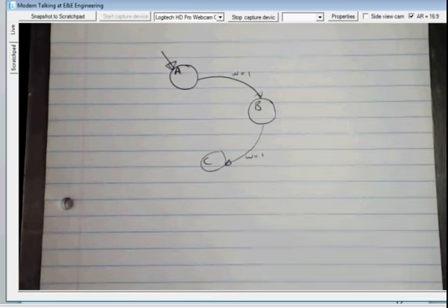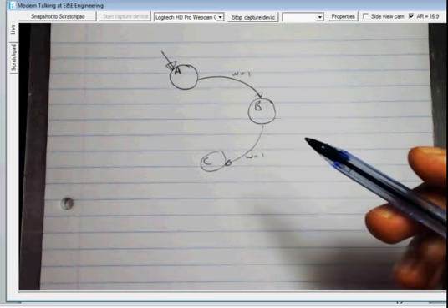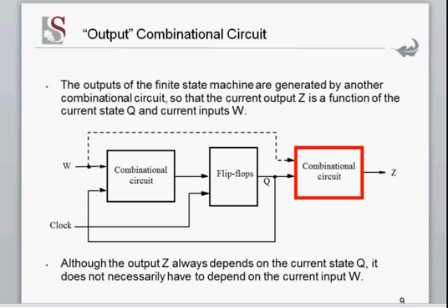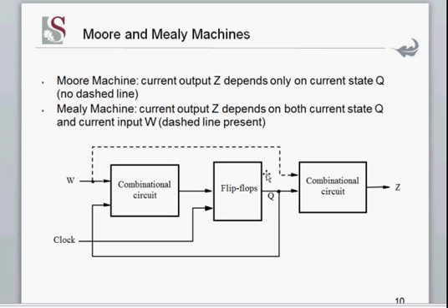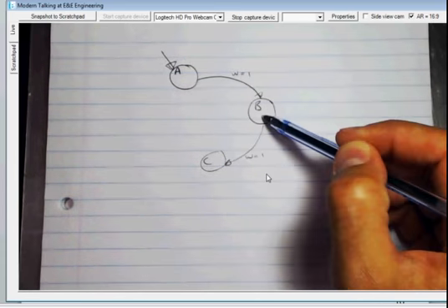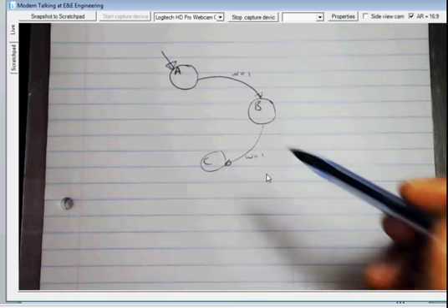And a very important thing to understand here is these state transitions occur on the clock edges. If you just go back to this block diagram, you can see the next state is clocked through into the present state when there's a clock edge. That's how flip-flops work. A flip-flop says if there's a clock edge, copy this side, paste it on this side. This is how it works. So these transitions, it's implied, it's never written down. These transitions happen on clock edges. This is the input, it was there on a clock edge, so it transitions.